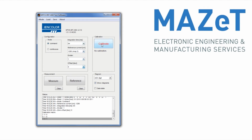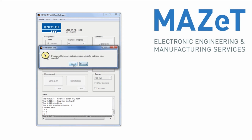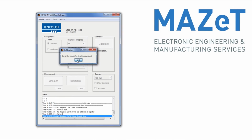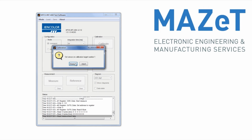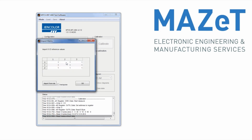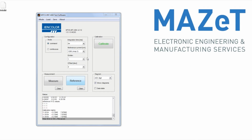With the ideal setup in place, the measurements can be performed by a 10 or 2 degree observer. The next step is to measure or import calibration targets. The user can choose the number of calibration targets and start with an offset, a dark measurement. The following step is to measure the chosen number of targets. After the measurements have been performed, one needs to import or enter the XYZ reference values measured by the spectrometer. A data file with the specific calibration information is saved and can be used for further reference. Changing elements, such as integration time or reference current, require a new calibration.